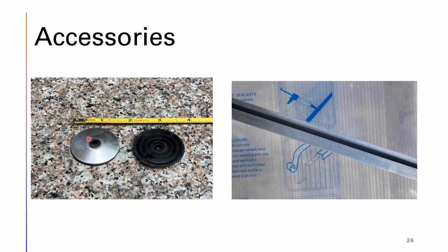And I have 2 varieties. This is a 1.5 inch diameter. I mainly sell the 1.2 inch. It's just more convenient. But you have to use these. If you're going into wood, you'd use just standard tin metal roofing screws. If you're going into steel, like galvanized steel frames, you'd use those screws I showed you before.